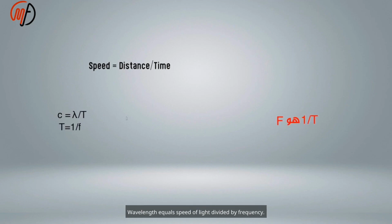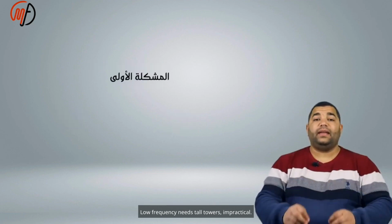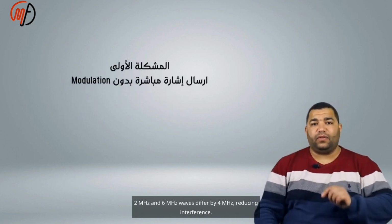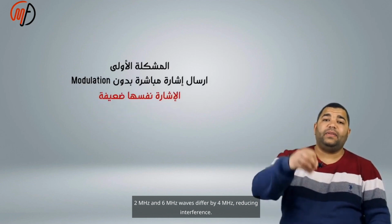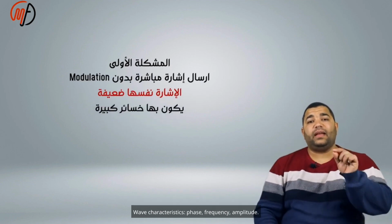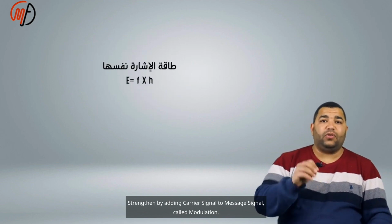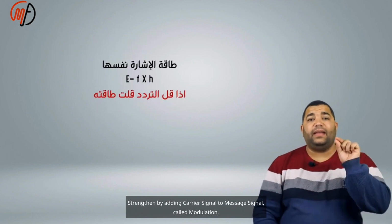Wavelength equals the speed of light divided by frequency. Direct signal transmission is weak and loses energy. Low frequency needs tall towers, which is impractical. High-frequency interference is less. For example, 2 MHz and 6 MHz waves differ by 4 MHz, reducing interference. Wave characteristics such as phase, frequency, and amplitude are strengthened by adding a carrier signal to the message signal, which is called modulation.